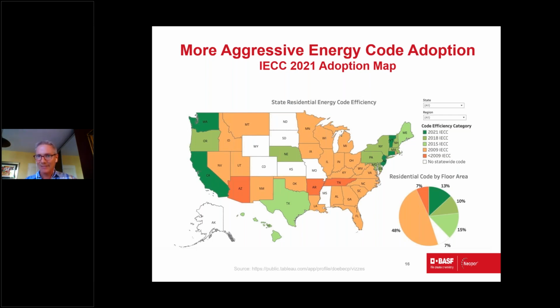So remember the 5 air changes per hour in the warmer climate zones and 3 air changes per hour in the cooler climate zones. And then in the 2012, every 3 years, these codes update, these model energy codes, and we added in continuous insulation and additional improved insulation requirements in both the wall and the roof and the building envelope and even in the slabs.